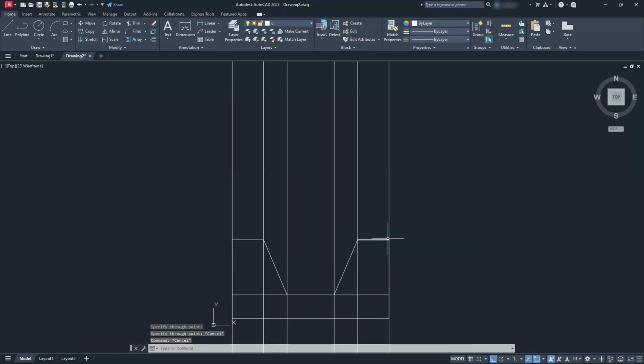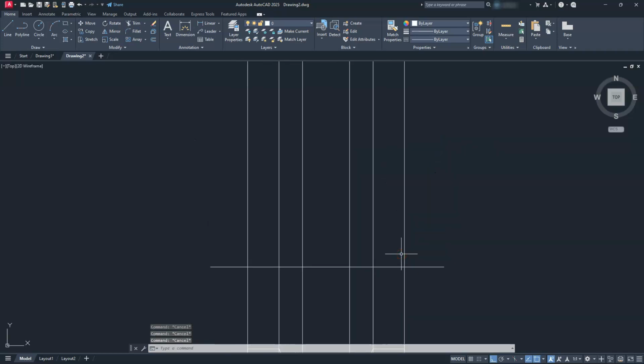And that should be all the endpoints I need to create the top. Let's start by creating a line somewhere above the top going straight across. So just make a horizontal line there. Let's come down. Let's go ahead and offset the distance of this line, and that offset distance should be 50. So I'll use a regular offset. The distance is going to be 50. Select this line here, and then click above it.